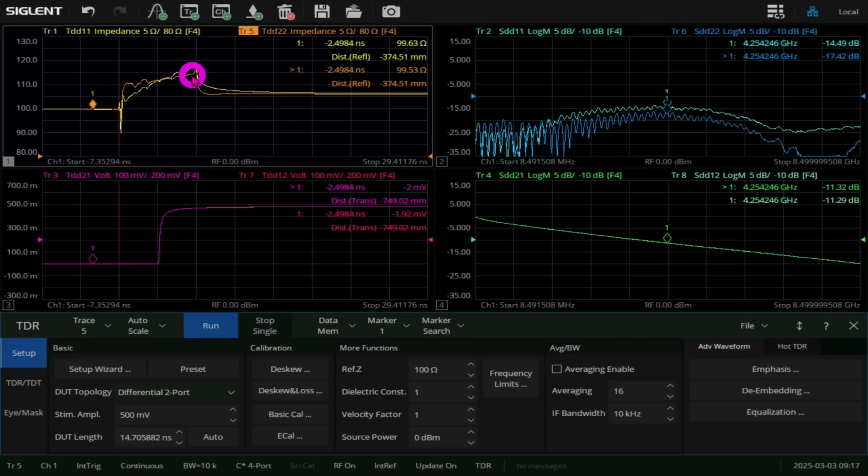And that's to be expected because we do have some connectors, and we also have the SMA connector that's soldered onto the PCB, and there's going to be a little bit of discontinuity at that point. But everything looks good. Remember, this is as a function of time. At the bottom, we see our step function. After some delay through the channel, it arrives and does have this low-pass filter characteristic to it. That's also to be expected because we are using a 1.5 gigabit per second channel. So it's going to have some low loss, which we will see.